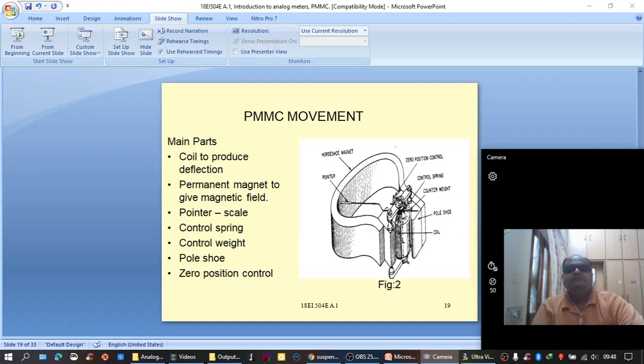Because of this variation in length on the two sides, where the pointer is hinged or connected here, when the pointer starts deflecting, the weight of the pointer on this side would be more compared with the other portion when additional weight is not placed on the second side.